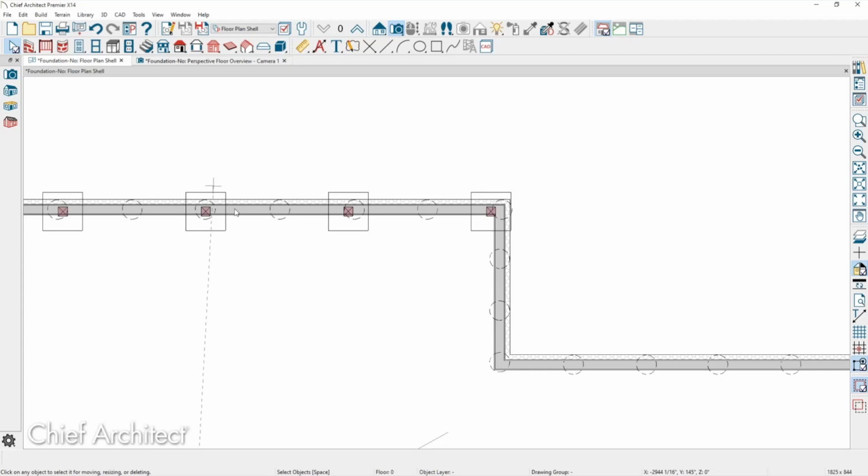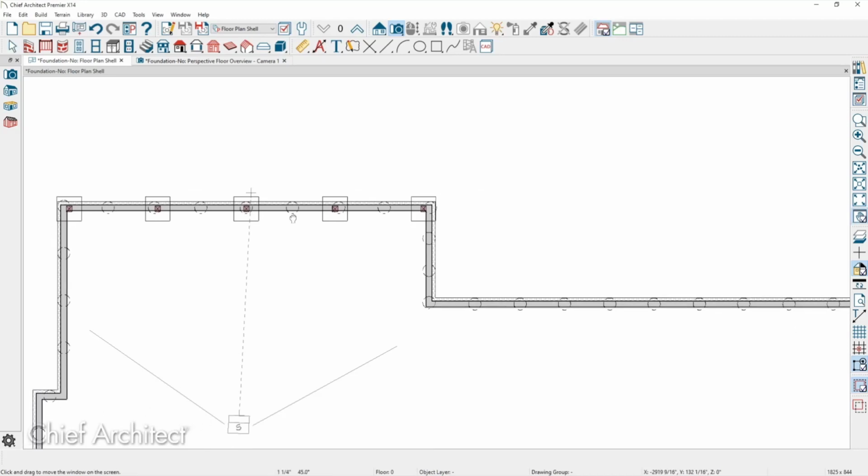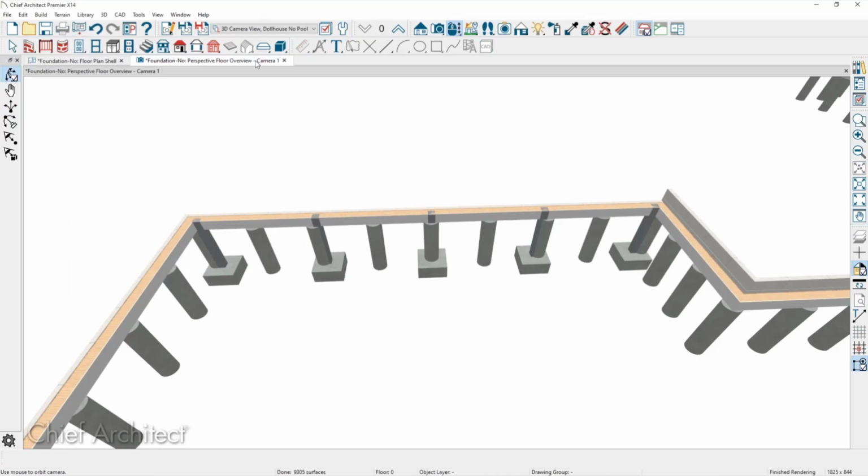I'm trying to figure out a way to get it done without having to do it manually, drawing in. So what I resorted to do was to use, as Scott said, a general regular strip footing setup, create the framing, and then delete the walls, which would then leave the framing in this position with my posts in line with it. That's what I resorted to do, because I'm just trying to figure out if there's a way to get it done automatically as opposed to doing it manually every time. Sure.